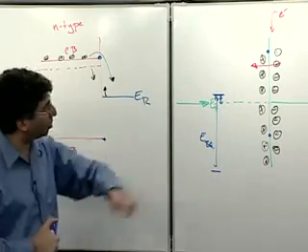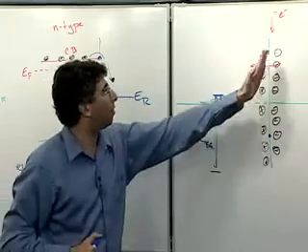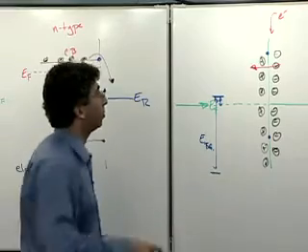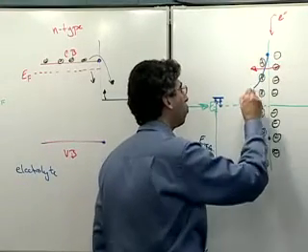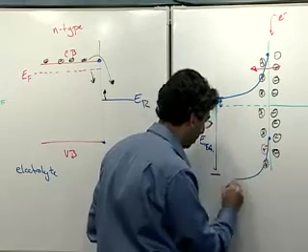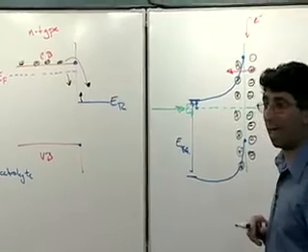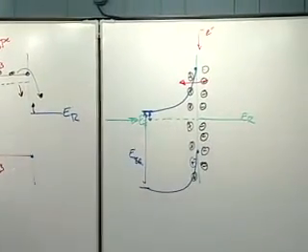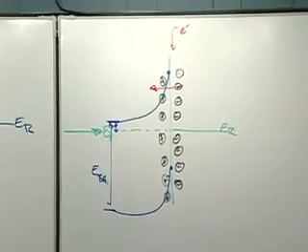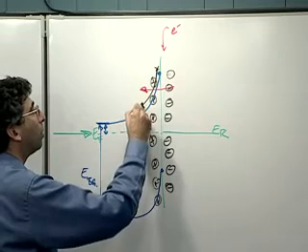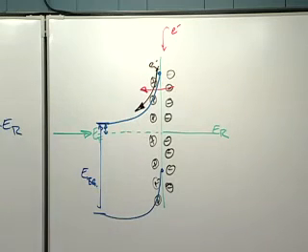Okay, but at the surface, I have set these potentials, and I have imposed an electric field at the surface, which is going to change the energy of the surface. So I connect everything together so that the band gap stays constant everywhere, and I have this band bending. And all that band bending is saying is that, again, if I take a test charge and drop it down here, an electron, it'll roll down the band. On the other hand, if it's a hole, it'll move up the band.